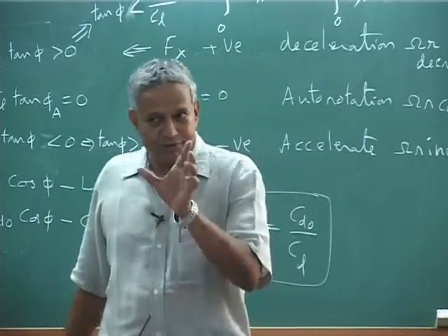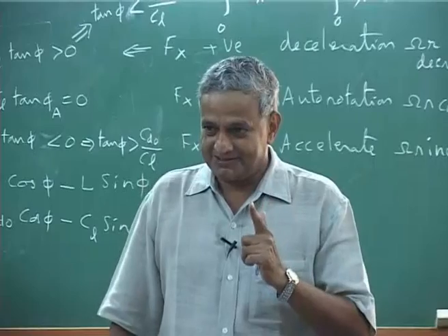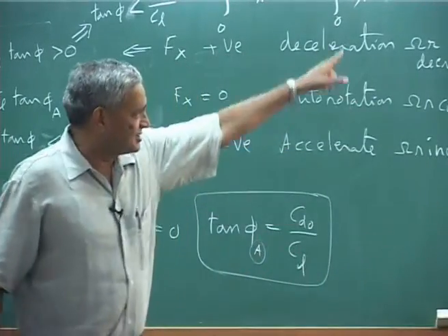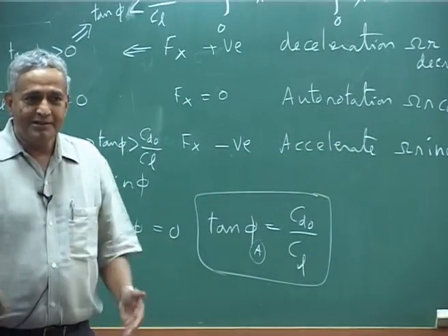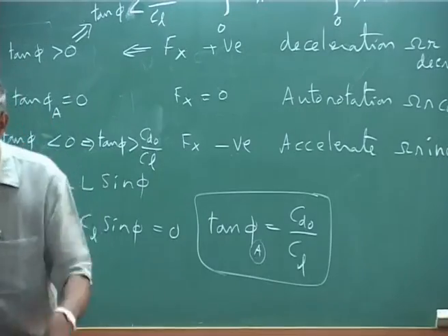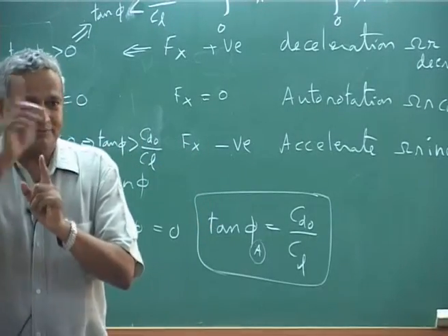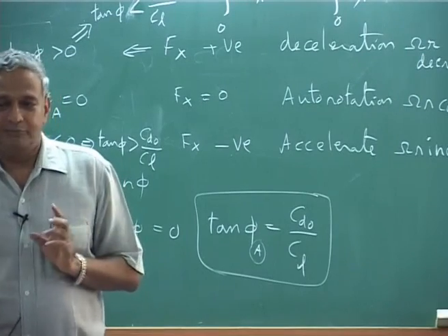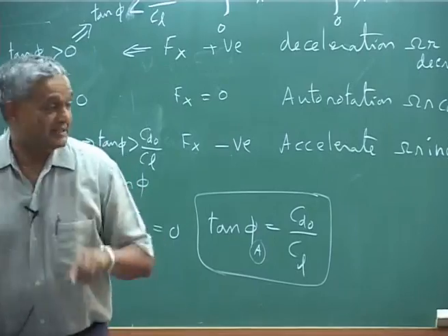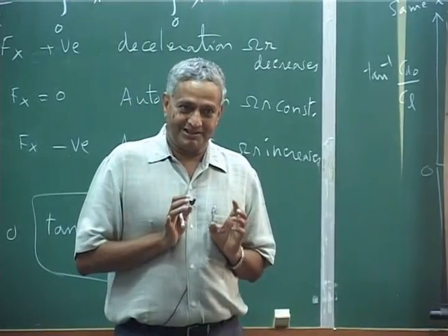That is why this is shown to the pilots usually, because this is airfoil characteristic, CD naught, because you are not doing anything auto rotation, you are just plotting that, and at the minimum point you say, okay, hey, the pilot should immediately dump the collective below, but then auto rotation is stable, rotor will continue to rotate. But what RPM will it achieve? That RPM depends on what phi value you are operating at, okay.